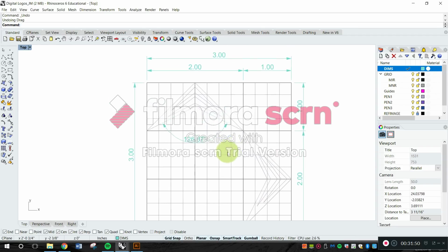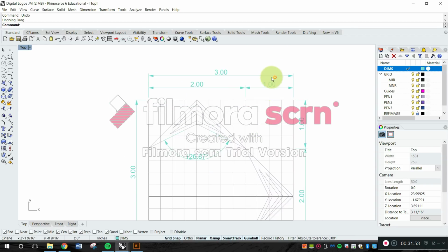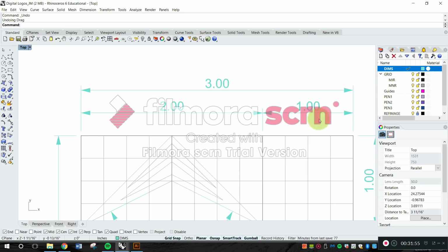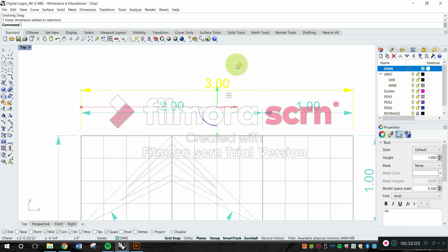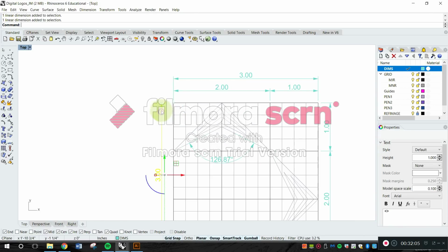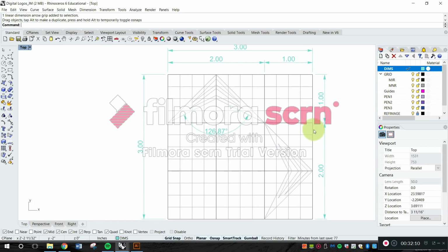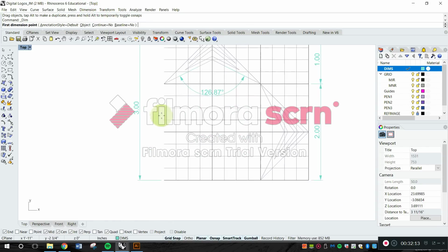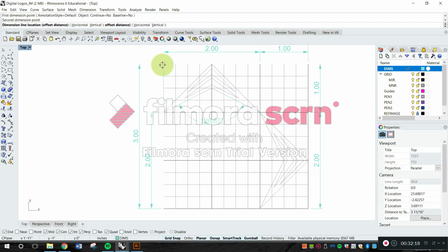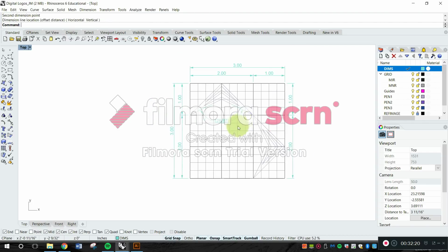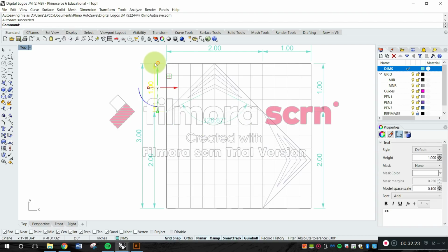Additionally, when you're dimensioning and you stack them like this, you want to go from a smaller dimension to the largest one. What do I mean? If I wanted to bring those dimensions, these ones, and put them on the same end, I would do it as such, and that right there.